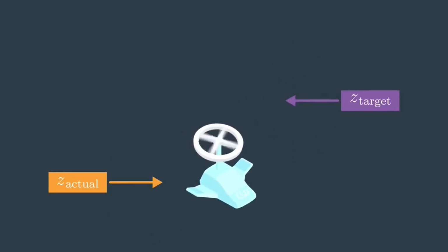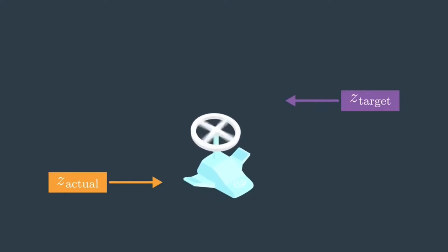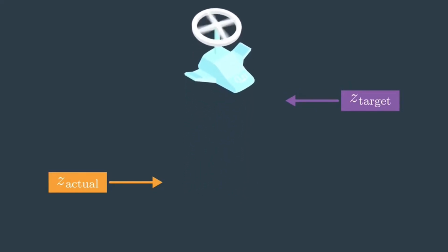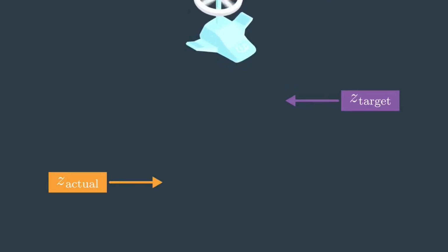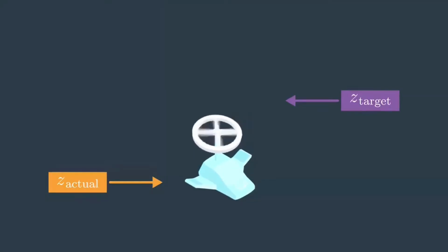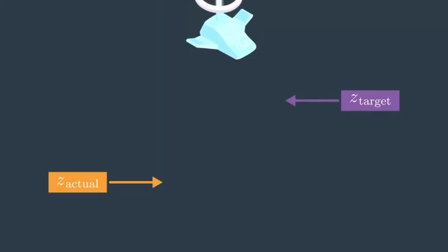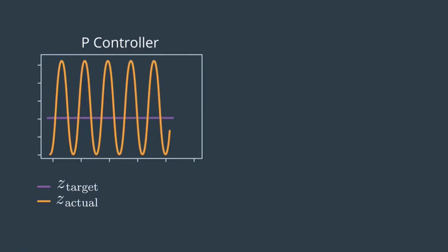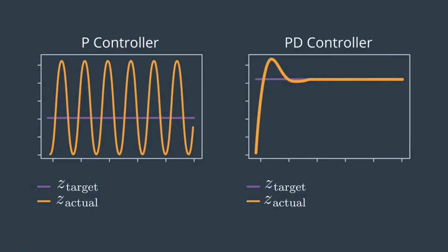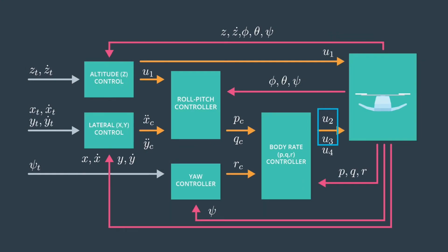However, depending on this concept alone is not enough, as it will result in the drone overshooting beyond the target location. Due to this overshoot, a new difference in distance will be introduced, which will force the drone to go back to its target location and yet miss it, resulting in an unwanted oscillatory movement around the target location. What we need is a controller that will actually stabilize the drone at the target location. Such a controller is called a PID controller, which takes into consideration the covered distance and the change in velocity to adjust itself accordingly. Eventually, the controller will look something like this.